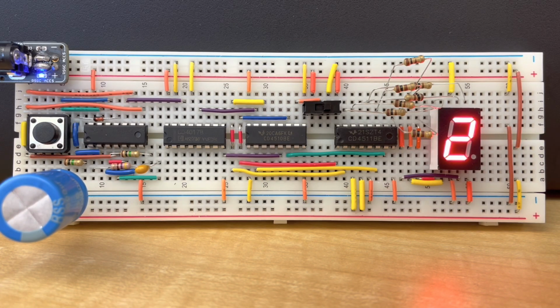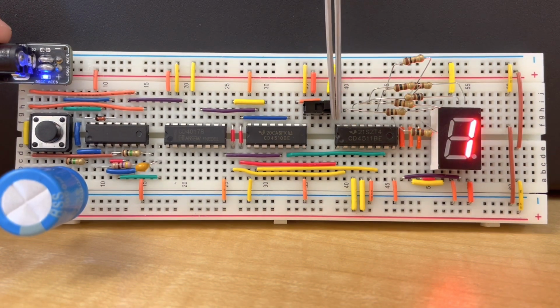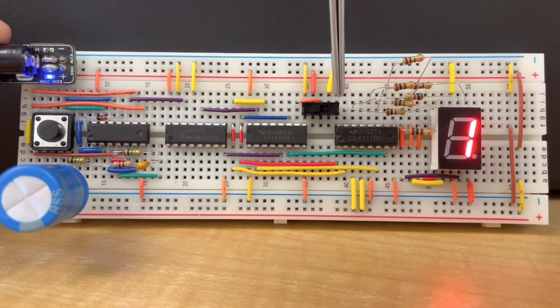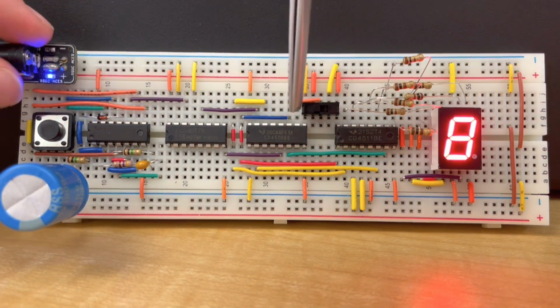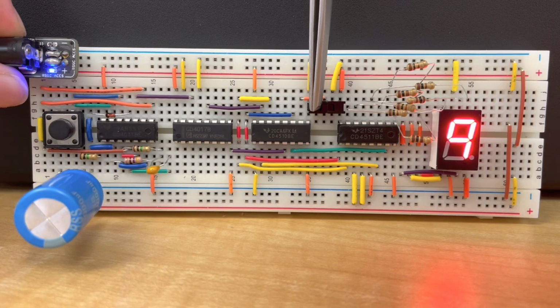If you would like to activate the decimal point, all you need to do is add a resistor coming from voltage. When connecting a 7-segment display to a circuit, it is important that resistors are incorporated. 7-segment displays are condensed LEDs with either a common voltage pin or a common ground pin. Due to this, the 7-segment displays need to have a resistor to prevent the component from drawing too much voltage and blowing up the LEDs.